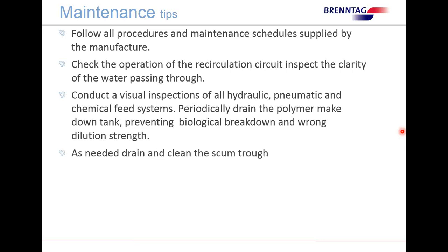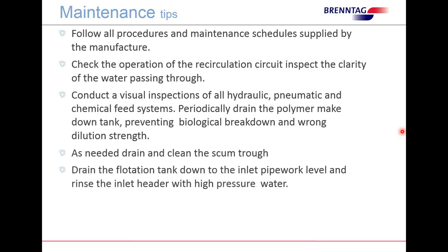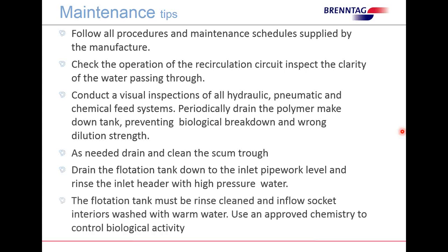As needed, drain the scum trough or area. Make sure that stays clean. It's good every now and then to periodically just hose it out. Drain the flotation down to the inlet pipe level. Rinse the inlet header and try to high pressure the header. Again, trying to keep it clean, trying to keep from uneven distribution. And then lastly, the flotation tank must be rinsed or cleaned, and the inlet header interior washed with warm water. If needed, use an appropriate chemistry to control any biological activity so you don't get bugs building up in your system.